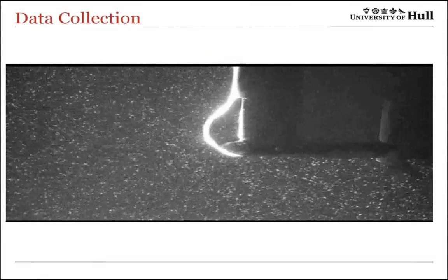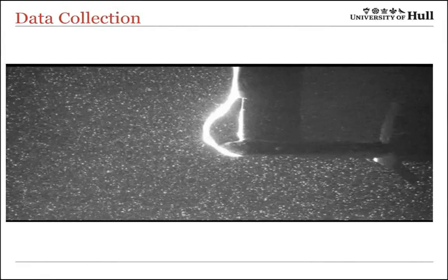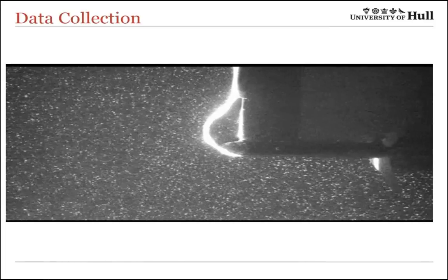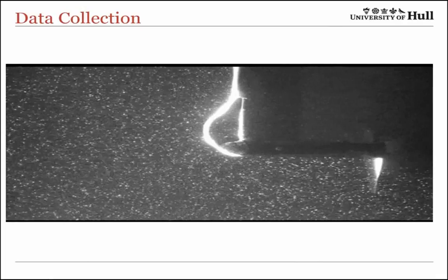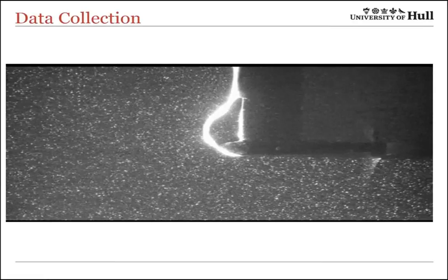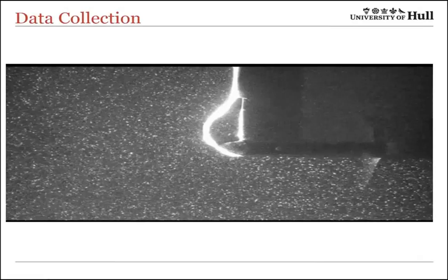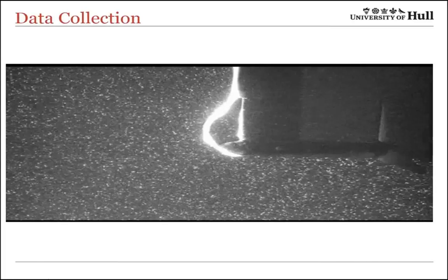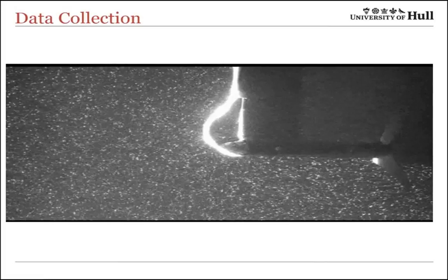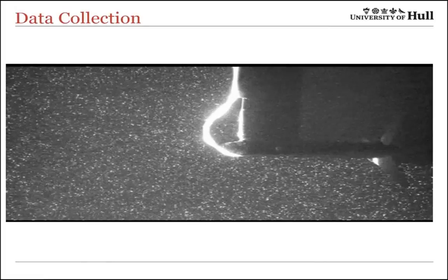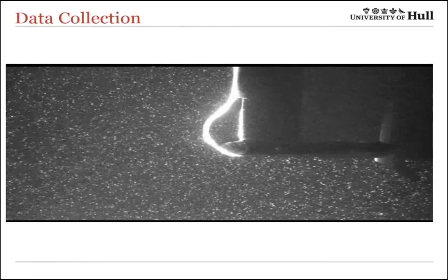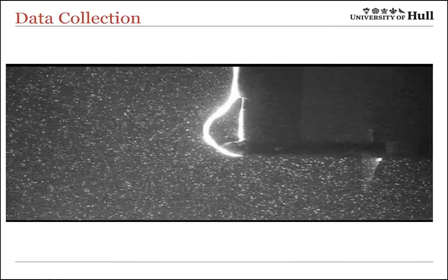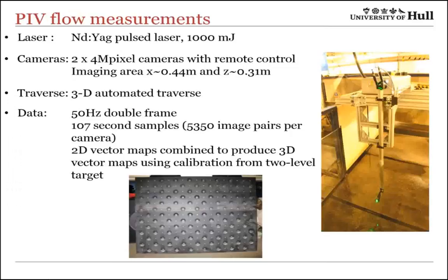This gives you a really slowed down video of the sorts of quantification we're doing. Apologies for the codec on this, it didn't work so well, so the quality is not quite as good as it can be. But it gives you the overall idea. This is the turbine swinging round, obviously, and these are the particles within the flow, neutrally buoyant particles carried by the flow, that we use with a sequence of images to essentially quantify the flow structure and the turbulence within the domain.